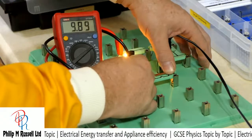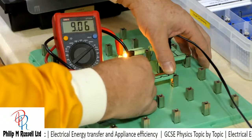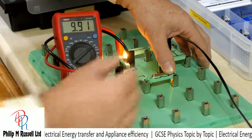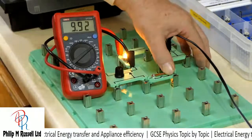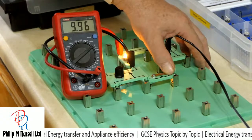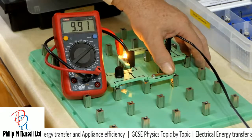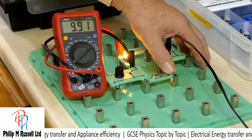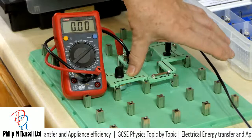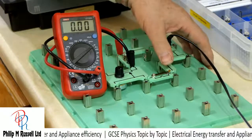If I adjust this, I've got about, on a minimum here, about 9.96, as near as I could get 10 volts going through, and that means that 2 volts, or 2 joules of energy per second being used up.